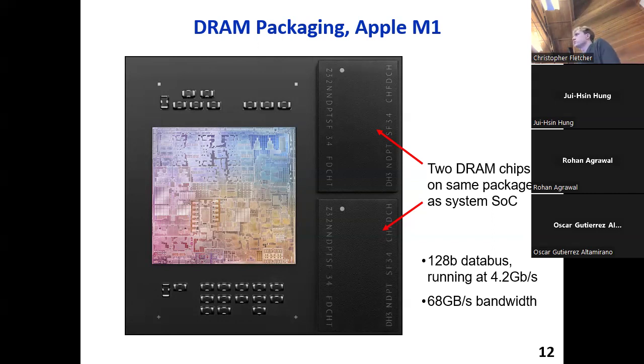Yeah, the DRAM controller does the write back itself. We'll see exactly where it does the write back. And there's some flexibility on when it's done, to hide the latency of that operation. Yep. Other questions? These are all good questions.